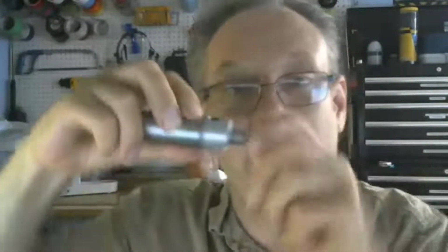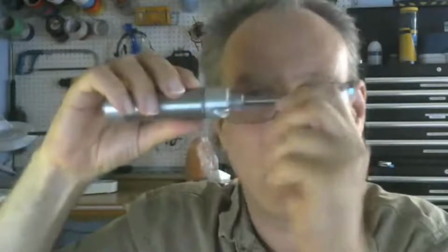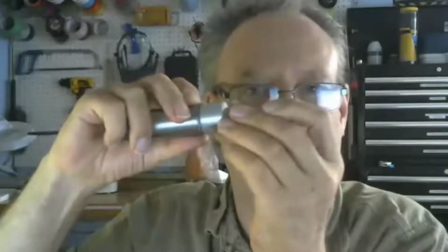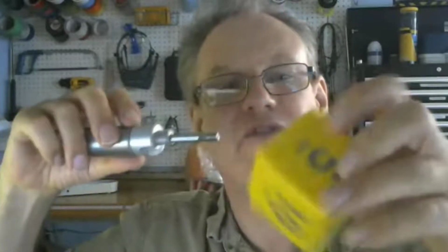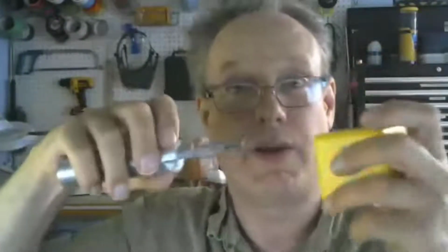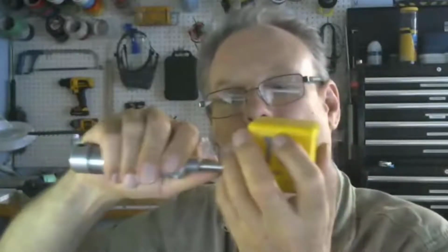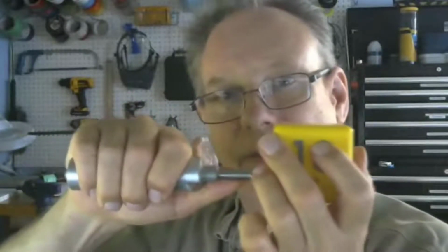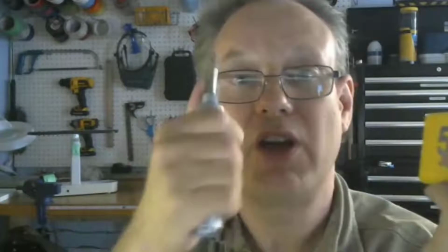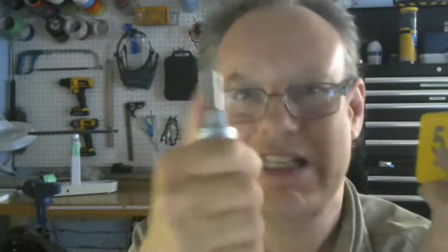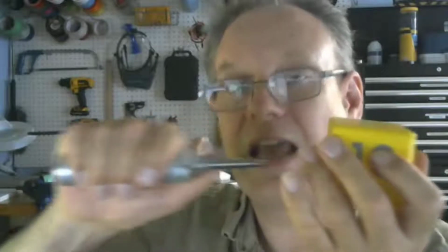When we clamp onto something, the cylinder extends all the way minus just a little bit, maybe half an inch, depending on how much this thing is going to deform when we squeeze onto it. So my operational extension distance, or what we call the rod travel, is different in a clamping operation.